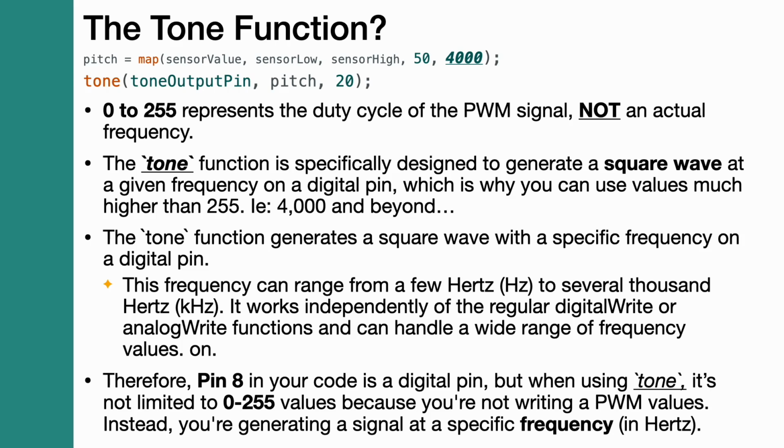And what we're talking about with pitch, which is really our frequency, is how often that value can be pushed into that pin. So let's say that the value, for the sake of argument, is 128. That's well within 0 to 255, no problem. If I send that value of 128 to the pin 4,000 times a second, that's okay. I haven't extended past the value of 255. I've just given it a value that it can easily handle, 128, and I've given it to it 4,000 times.